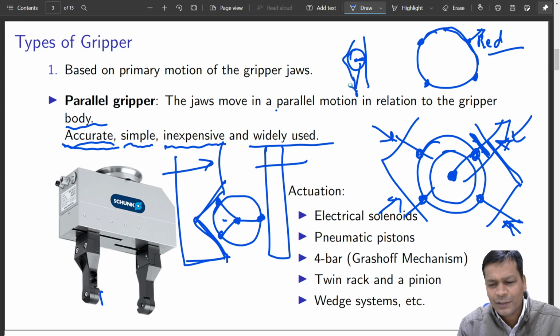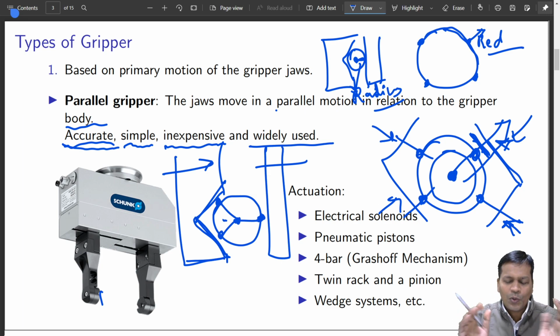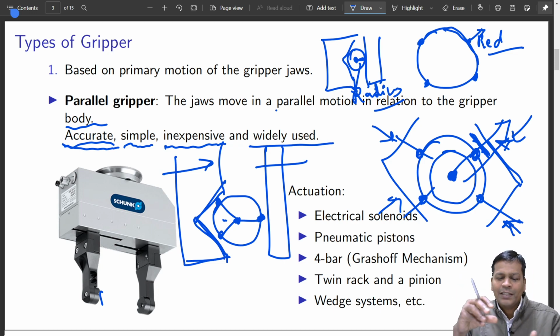The center line of this cylinder will vary by an amount equal to the radius from the flat finger, is it not? So that is why this changes. Every time you hold a different cylinder, it is held at a different location. So it becomes very difficult to precisely insert this. If it has to be inserted into a hole, you don't know the axis because radii are changing.